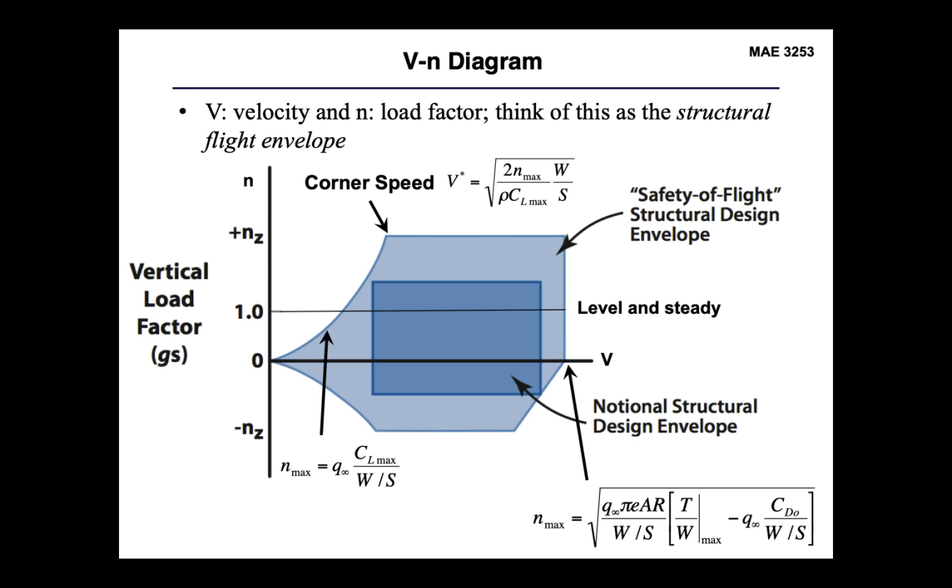And you can kind of think of this as the bounds between your aerodynamic limits on the left-hand side and the structural limits on the upper bound of this. So where these two meet gives you essentially your best maneuvering point. It's where you're flying the slowest, and so if you go back and look at your bank radius and then the bank rate that you have, that's going to give us your most maneuverable point at that highest sustained maximum load factor that you have.